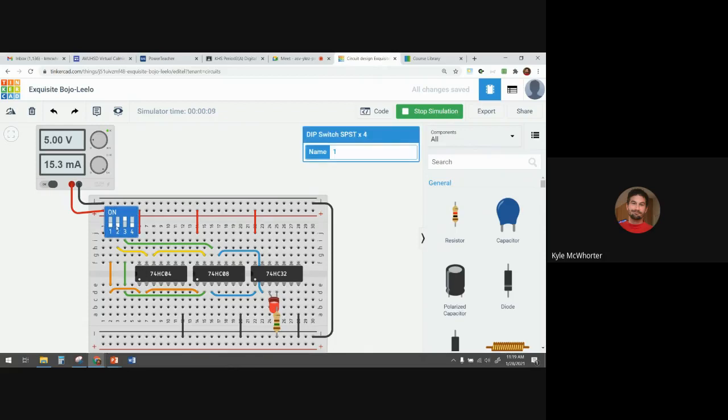Okay, so z and not one of those. Right now I have z and I have not x, so my light should be on. Right now I have z, but I don't have not x or not y, so my light should be off. So then you'll just check out your circuit, make sure it matches the truth table like that. So hopefully going over the entire process will help you remember all the little steps.